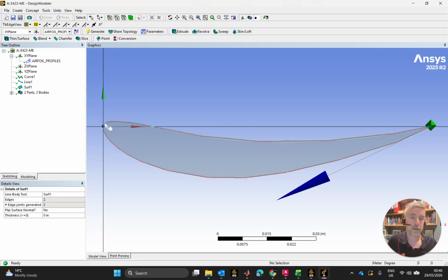Why? Bring it out any further, the competition organisers and scrutineers rightfully would be concerned about driver visibility, the driver's ability to see the track in front of them. If there's a big massive wing in the front, it doesn't really help to see cones that you need to drive around. So yeah, 700mm is as big as I can make this airfoil. Now if I make it 700mm, that means that the trailing edge is going to be rubbing, well, it shouldn't be rubbing the tire, but it'll just be coinciding with the tire. Okay, which I don't want.